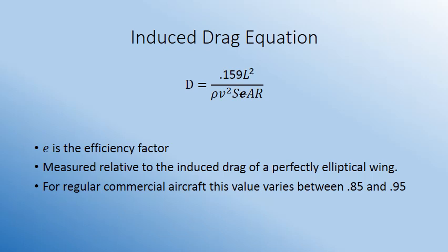This number, also known as the Oswald efficiency factor and sometimes referred to as the wingspan efficiency factor, is the ratio of the amount of lift generated by the wings over the maximum theoretical value. This efficiency factor is based on the lifting line theory of Prandtl, which states that the maximum theoretical value is the amount of lift generated by perfectly elliptical wings. Based on this theory, it can never be greater than 1. However, it is still a matter of study and has not yet been determined whether the maximum theoretical value is truly that one produced by elliptical wings or not.